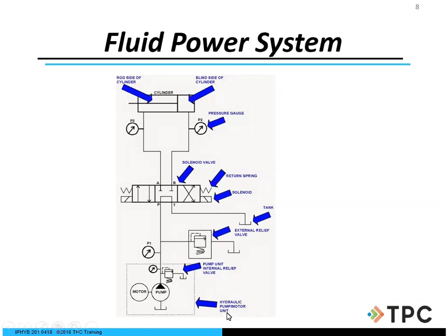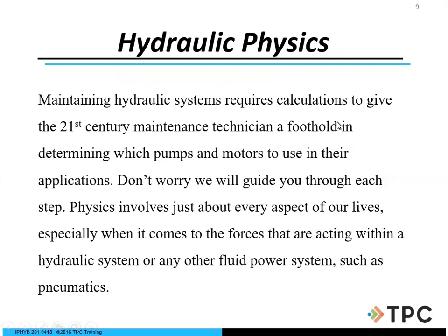As you do know, I went from the bottom up. And so that's how you read these hydraulic schematics, because you're reading from the bottom up versus an electrical schematic. You're going to read from the top down, left to right. On these hydraulics, you read from the bottom up. This is where my motor and pump is, and pumping fluid all the way through. Critically important, right? Knowing how to read your hydraulic schematic and knowing some of the components in your system. Critically important. And so maintaining hydraulic systems requires calculation, so don't let that scare you.